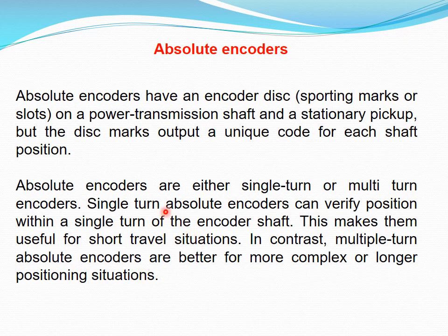Once again, a single turn absolute encoder can verify the position within a single turn of the encoder shaft. Whereas if you are going for a long position travel situation, you are going for a multi-turn encoder.